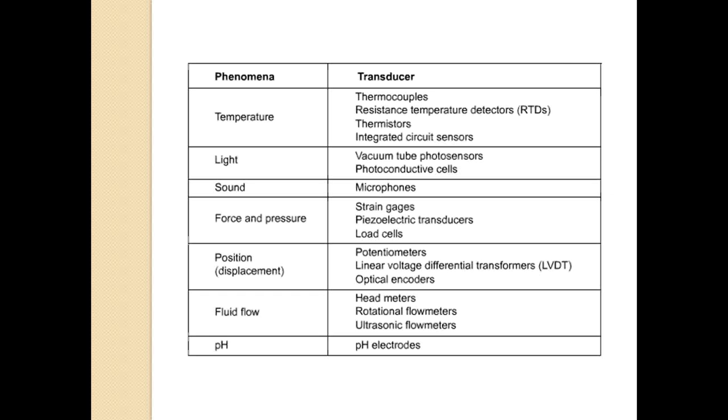In the last session, what we discussed is that I had a PIR sensor with me. PIR is a passive infrared sensor which has three terminals: VCC, ground and Vout. VCC determines the input supply voltage of the sensor. Ground is your reference point against which you measure your data. Vout collects the data from the external environment or physical quantity and gives the output in terms of voltage. Since I had three terminals, I needed to capture this data and give it to my DAC system.